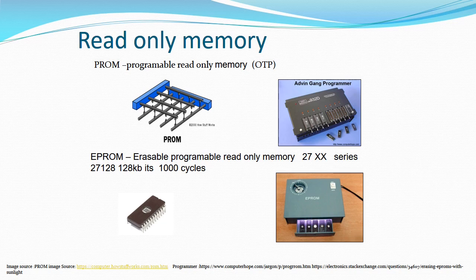The second memory is called UV-PROM. UV-PROM stands for Ultraviolet Erasable Programmable Read-Only Memory. These memories can be programmed using a programmer. To erase the content within the IC, we should place these ICs under a UV light source for 20 minutes or so. As you can see, the UV-PROM has a quartz window, which is shown in the slide. Through this, the memory is exposed to the UV light and the memory is erased. This window is covered when the memory is in use. It requires a separate programmer to store data.